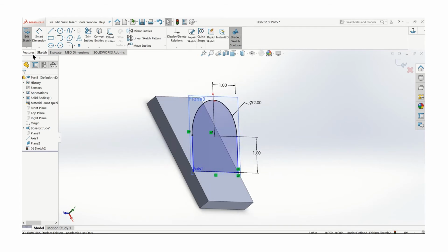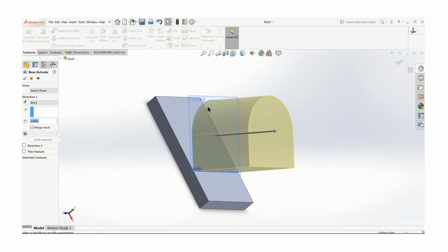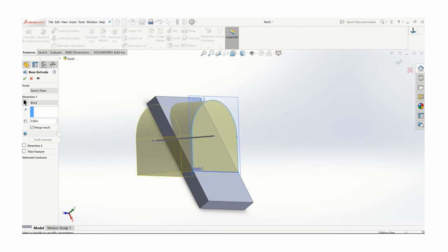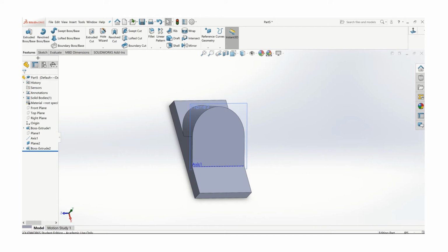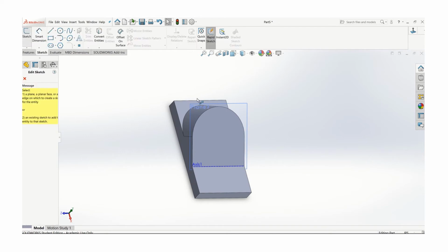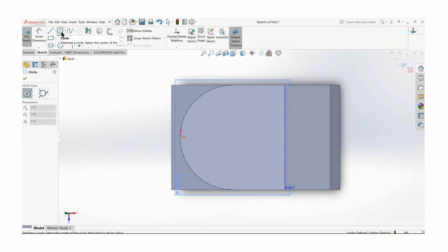And let's go ahead and extrude that now. Oops, gotta exit our sketch. And we'll want to extrude it up to next. So go up to next. And we do have a hole in that. Let's go ahead and put the hole in that surface. That's a 3/4 diameter.